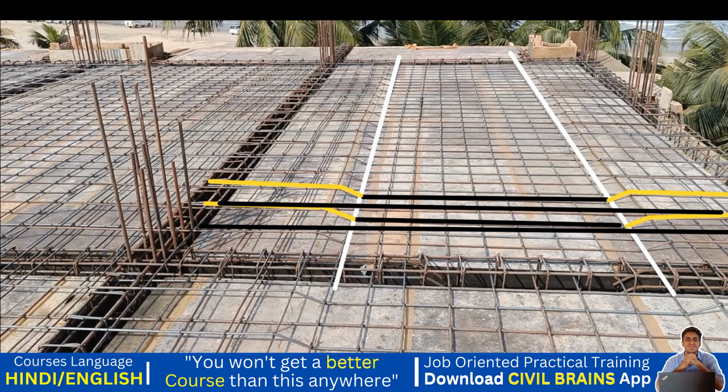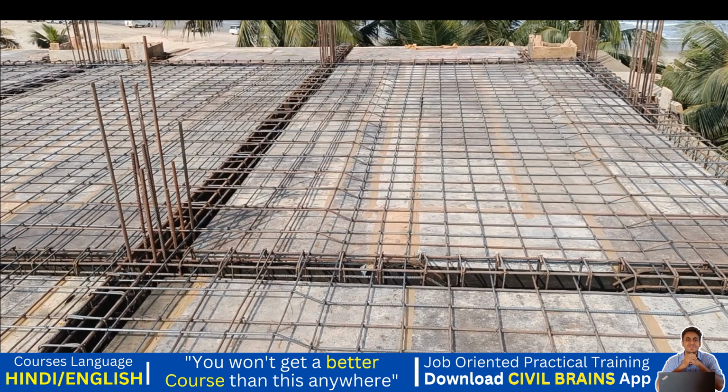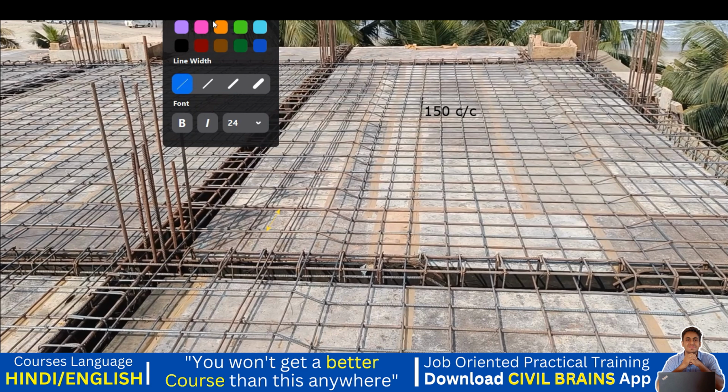Now, whatever negative bending moment you have given, there the steel requirement was more. By doing a crank bar, the spacing between these, I'll tell you one more thing. This spacing you should keep at 150 center to center. The distance between the crank bars has to be 150 center to center. But practically, since the spacing is double, this is not 150, this is 300, right? Similarly this is also 300.